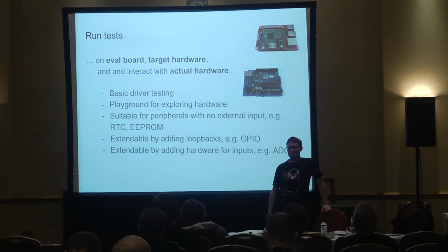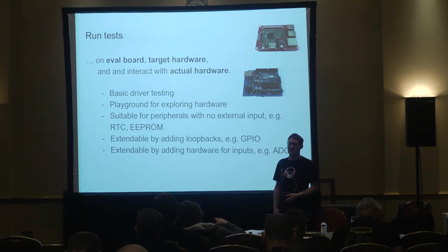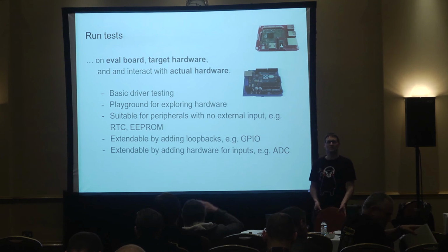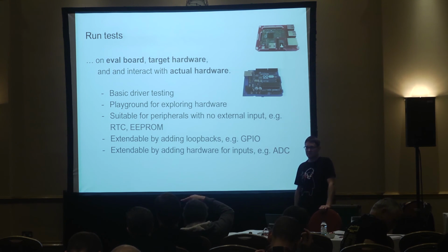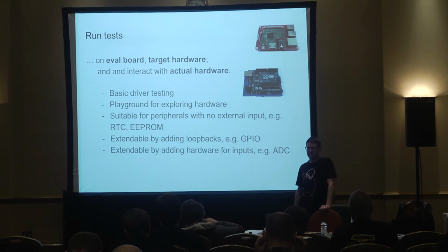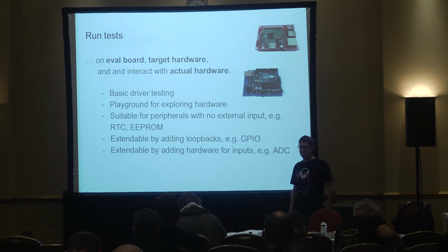So I had to create a full emulator for that chip by the specification, which did exactly that, but allowed me to inject bit errors and all kinds of bad stuff, and that was tested completely outside the environment. While I tested that, I only had to replace the 7 functions for the commands on the chip, and all the other code was just compiled for the host and the other for the emulator.